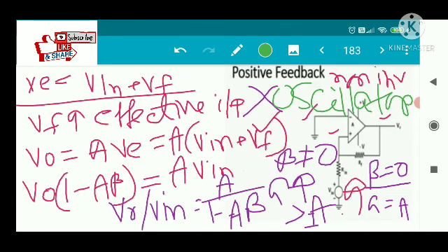Okay, so from these two examples you can easily see how we can implement the op amp with feedback. And previously you have well understood that negative feedback can be used for different purposes. If you want to operate the operational amplifier in the linear region, to be used as an amplifier, and want to reduce the gain, increase the bandwidth, reduce the distortion, reduce the environmental effect, then we must use the op amp with negative feedback.